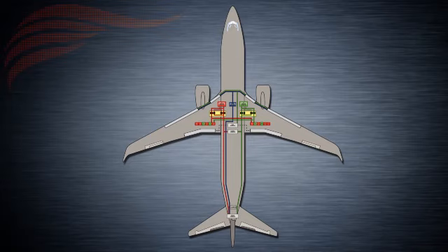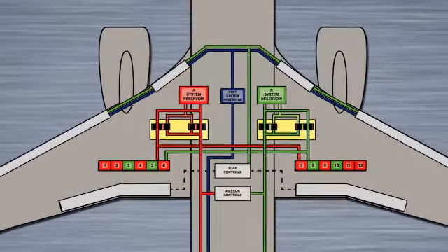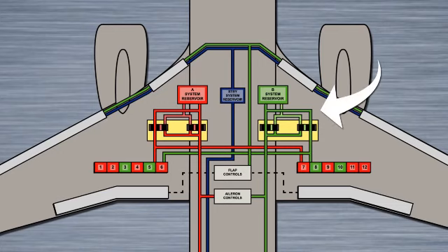Trailing edge flaps may be controlled by one of two ways: hydraulically or electrically. During normal operation, the hydraulic system B powers all trailing edge flaps. System redundancy is provided in a way by which if there is a hydraulic system B failure, trailing edge flaps may still be operated electrically through the alternate flap extension mechanism. This will be discussed further during this lesson.